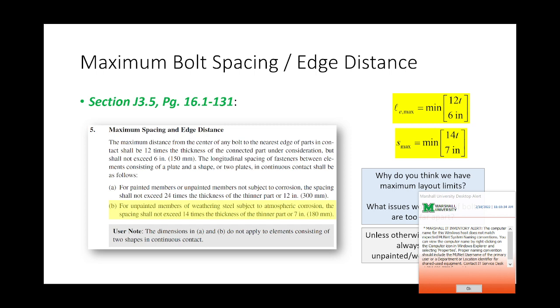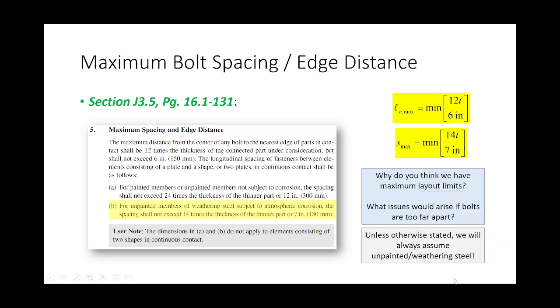Now, one of the things that DOTs require, though, is if you ever look at a bridge, where does the drainage happen? On the ends, right? That's why DOTs still say, I want you to paint the ends, because they want that extra layer of rust protection at the ends where the water's going to drain. Does that make sense? See, this is all real world stuff.